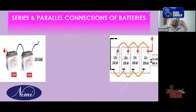Depends upon that. Normally our lead acid batteries are all 12 volt capacity. So with 12 volt batteries, if you want a 24 volt system to be adopted, you have to connect 2 batteries in series. आपको 2 batteries series में connect करना पड़ेगा. Positive of the first battery is connected to negative of the second. So between these 2 points, you will get 12 plus 12, 24 volt.